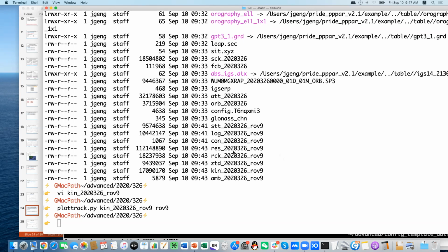After that, the code bias induced biases are corrected. For satellite-related code bias, they have been corrected for BeiDou-2. We use the model released by a German scientist several years ago. It's just a table to correct for the biases caused by the BeiDou-2 satellites. Then you can do the ambiguity fixing for BeiDou-2 satellites.